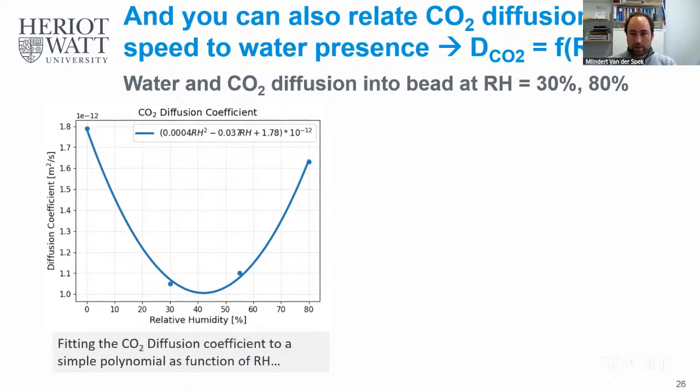The scalability is great. The oxidative stability is unknown to a large extent, and that's an issue, because not only does your material become less effective after time, but we know from solvent-based carbon capture that oxidative degradation also releases volatile gases. So ammonia is the most important one. I mean, you don't want a capture plant to emit ammonia. I mean, not more than any other industrial plant is allowed to, right? And also for direct air capture plants. And we don't know very well how much they degrade.